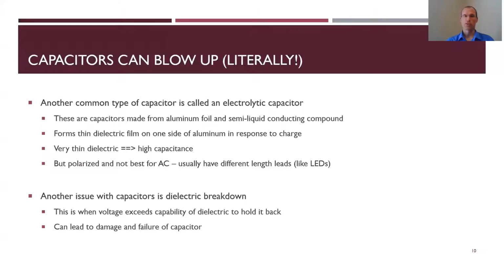I've been in rooms where capacitors have been blown up by students. I've never done it myself, but I've been in the room when students have done it. So be very careful with those. They're a lot like the LEDs, where one lead is going to be longer than the other one. And just like the LEDs, the longer one you want to put on the positive side to make sure that it's in properly. Again, if you put it in backwards, it's not going to do what you want it to do, and it may blow up.